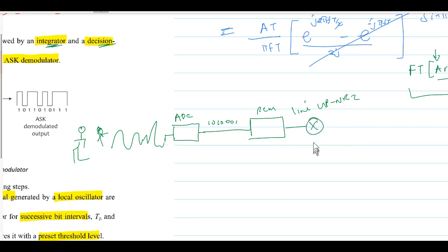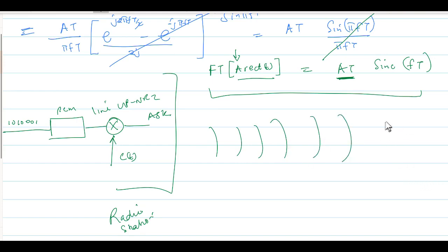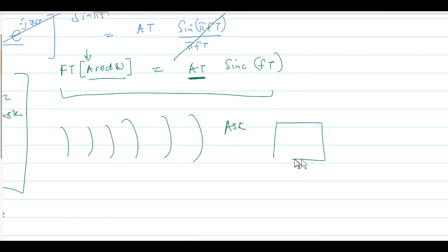This is multiplied by the product detector with the carrier signal, the one that we are calling c(t), that is locally generated, and therefore we are able now to have an ASK signal. So at the ASK signal, on the other side of the receiver, this might be, say, at a radio station that we want to transmit a signal. So it is traversing a long distance. Then at this side, we are receiving an ASK signal, and an ASK signal requires now to be demodulated. So this is the ASK message. This now we are calling the demodulator. The demodulator is the one that is supposed to convert the ASK transmitted signal to become the binary data streams that now can be used to represent the data that was initially sent to the modulator.